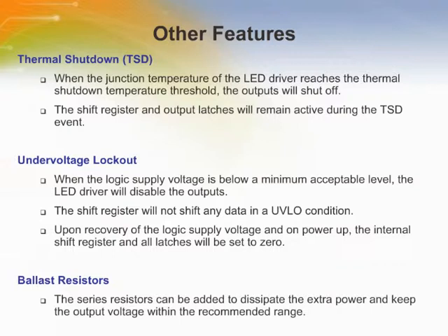When the junction temperature of the LED drivers reaches the thermal shutdown temperature threshold, the outputs will shut off until the junction temperature cools down below the recovery threshold. The shift registers and output latches will remain active during the TSD event. Therefore, there is no need to reset the data in the output latches.